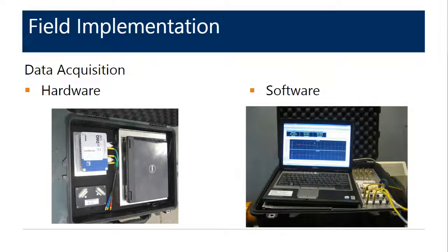For our data acquisition system, we currently use a system manufactured by HBM, their SOMAT eDAQ Lite unit. This provides a modular system to record multiple channels of data. There are many different varieties of data acquisition systems that provide the functionality required to record data. For field operations, it is beneficial to have a robust data acquisition unit that is rugged enough to withstand the field conditions and versatile enough to view data real time and enable data to be processed efficiently.